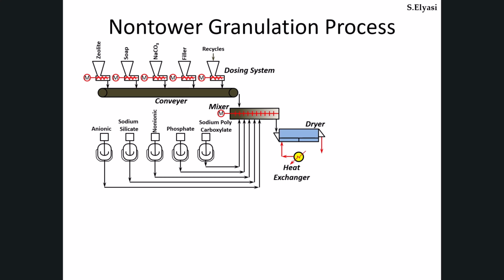If the steam is superheated, it first cools to its saturation temperature and then condenses on the inner drum wall. The latent heat of condensation provides most of the heating duty, so effective condensate removal via a siphon and steam trap is critical. If condensate accumulates, it creates a thermal resistance, lowering heat transfer, drying capacity, and product consistency.